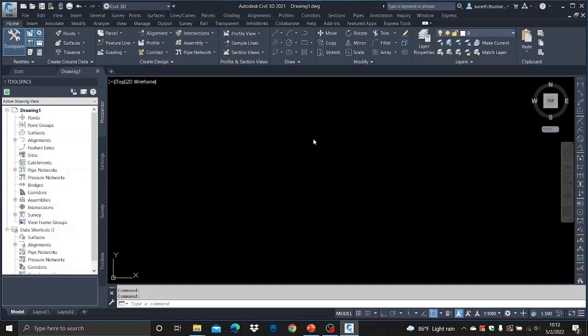There are some data that you are going to give. Sometimes in each 10-meter interval you are going to give the chainage or the station, and sometimes you are going to give the curve radius. In some agencies you don't give the curve radius in the drawing itself. Anyway, there should be some consensus, so your first drawing should be compatible with the second drawing and the third drawing. You cannot give the radius on one occasion and not on the other. No, you can't do like that.